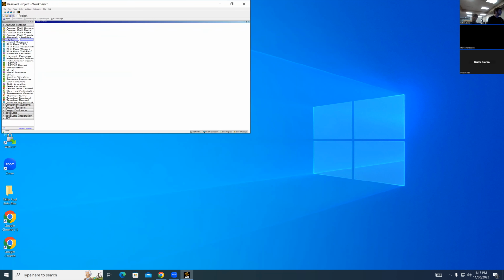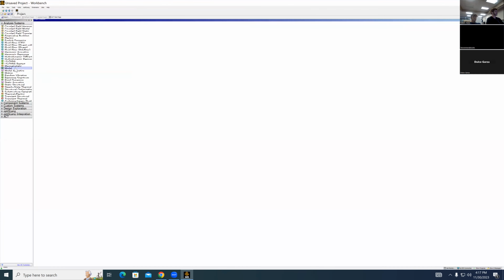This condensing on the side, you can actually fix it. We're not going to, because I don't want to do it live, but the way you fix it is you go to the ANSYS Workbench, right click it, hit properties, and go into the visual section. If you look up this problem, it's a very common problem to have. You fix it once and it never happens again.